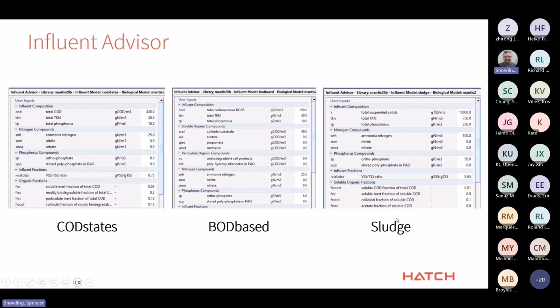And we also do have this one, just threw it up here just for input sake. So you can actually specify your Influent to be a biosolids line. Like basically you could say it's thickened WAS or something. And up here you have TSS, you'd enter in, we have it as a default of 10,000 milligrams per liter. And you would set some other typical numbers for that as well.